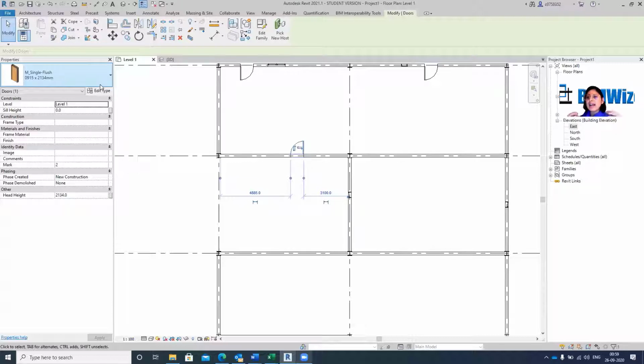And something that can come from the outside, that is not supposed to be built on site, is a loadable family or a component family. So let's say doors, windows, they can be manufactured outside and brought in. Your furniture, all the equipment that's being used, any entourage, any millwork, all that are component families.